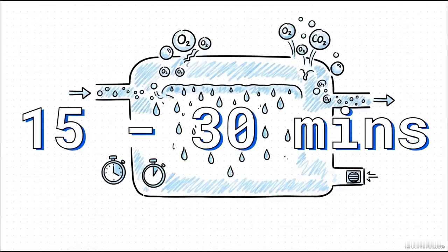But you know, this physical reaction, it isn't instantaneous. And that brings us to a third, totally vital metric, residence time. The water typically hangs out inside the Deaerator for about 15 to 30 minutes. This isn't a quick fix.